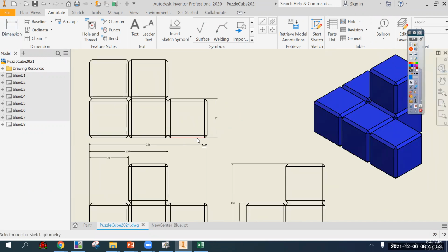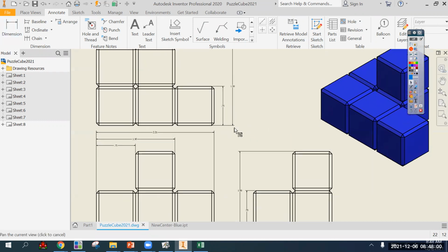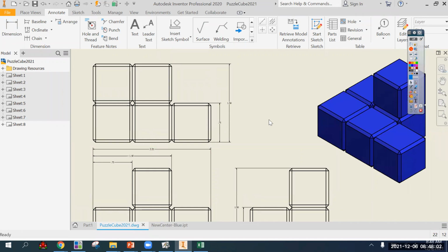Haven't really thought about it this way before, but if you stick to width dimensions on the front view, height dimensions on the right side view, and depth dimensions on the top view, I mean, that's a way oversimplification, but in this case, at least, it definitely works. But it's really more about width, left to right, every time something happens, take a dimension. And as you're doing those, you are working through the hierarchy of which is better or worse.